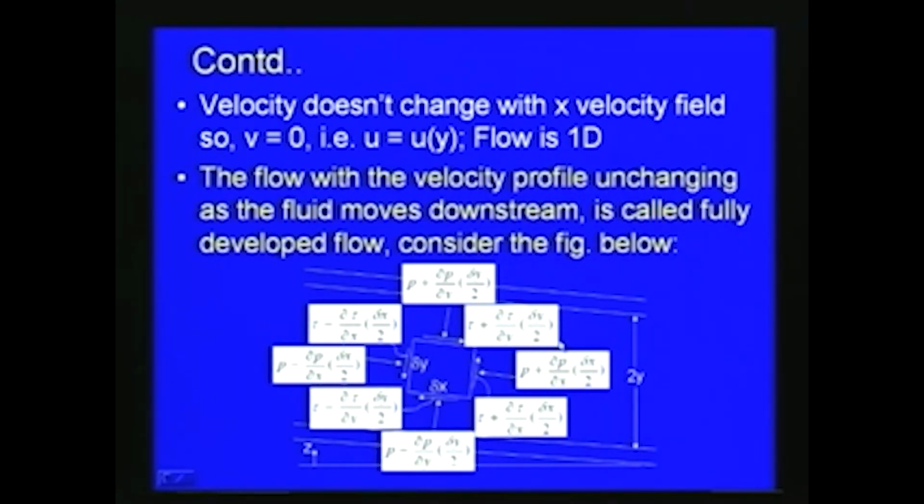So, for this particular case the forces acting are the pressure forces on the fluid mass, the mass of fluid which we consider, and then the shear forces, or the corresponding shear stresses on all the sides of the fluid mass. Now our aim is to derive an expression for the velocity variation, and here we are using Newton's second law.